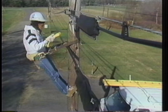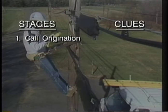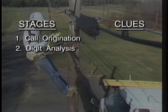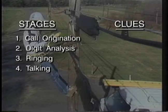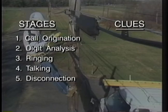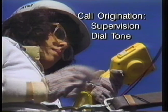By applying these major stages of call processing, a technician can play the role of a private eye to isolate a problem situation on a telephone line. By following a divide and conquer technique, the technician can compare the clues of the problem with each call processing stage until the probable cause of the problem can be isolated to one logical area. For instance, if it is possible to obtain dial tone on a line, then it's an elementary assumption that the first steps of a call origination are being performed correctly.